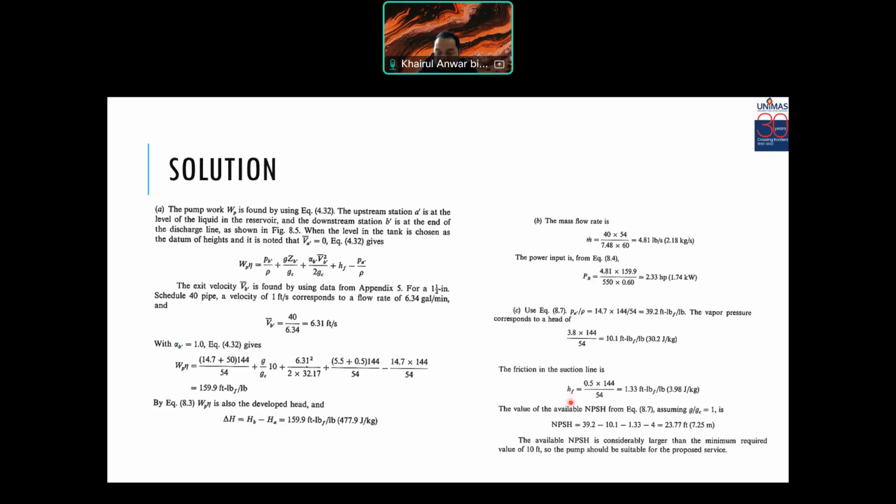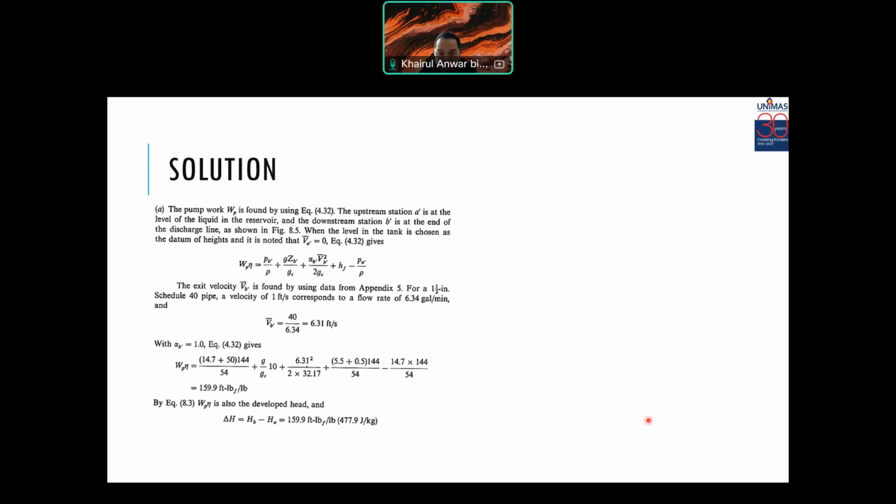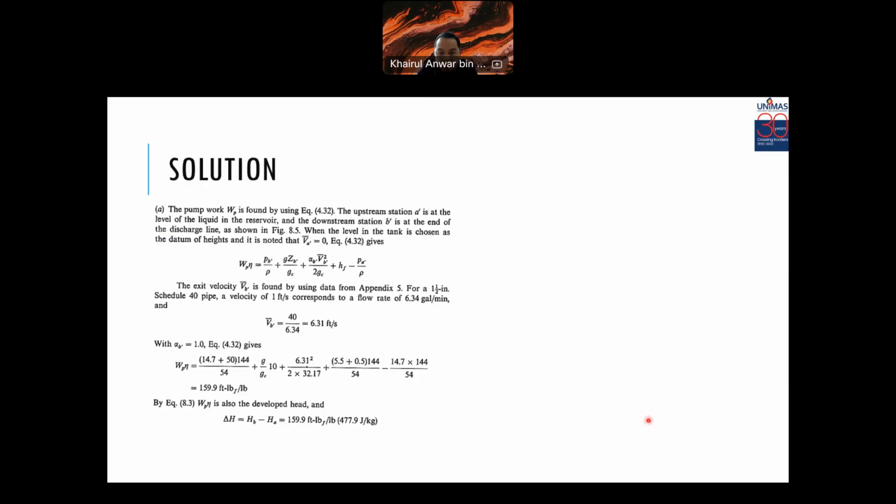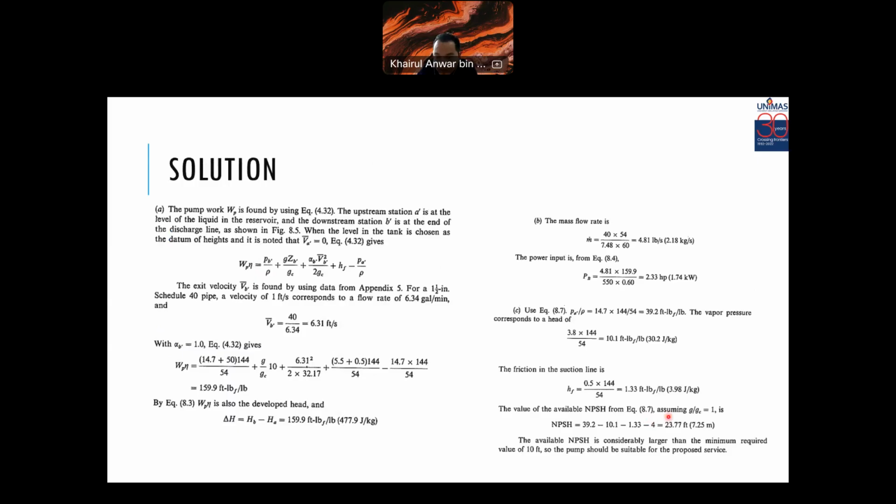Friction in the suction line, HF, and the value of friction from 8.7. See the last one, with g over gc of 1, then NPSH is 22.77 feet.